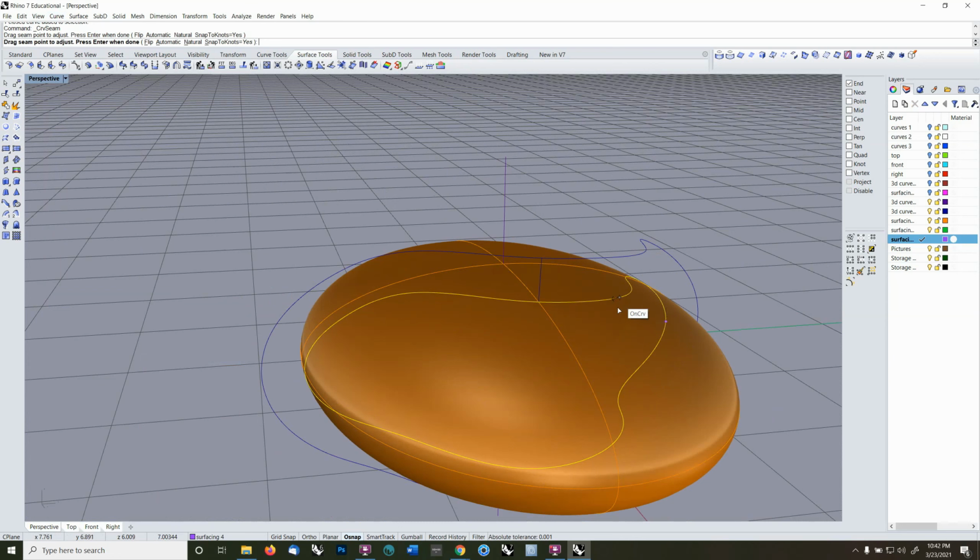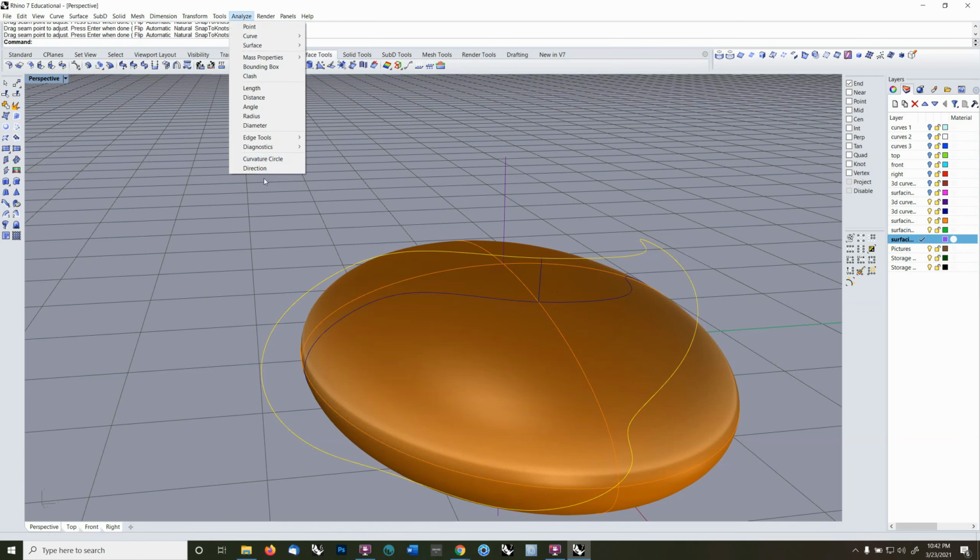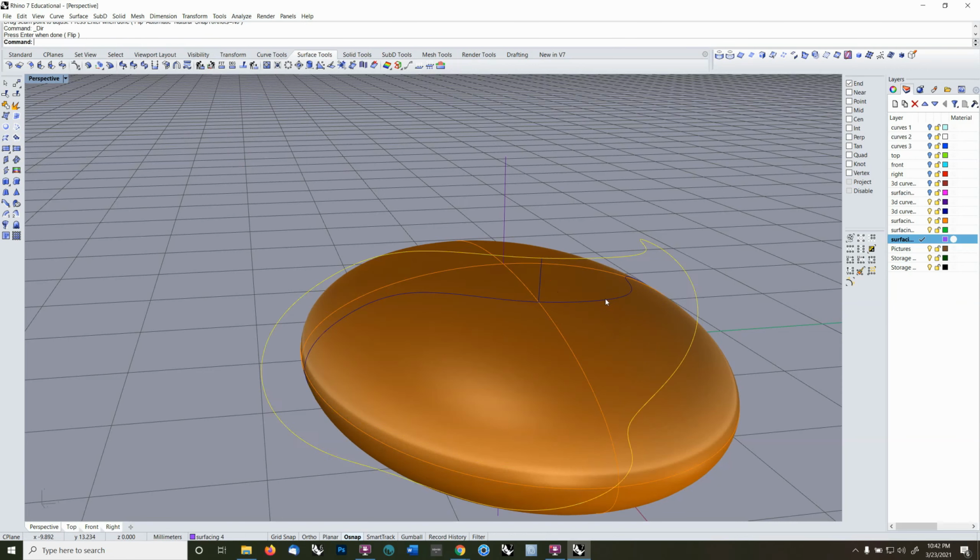It's right here. It's snapping to knots. That's why it won't go. Make sure that's always turned off. Snapping to knots is useless. It's completely useless. You'll notice these surfaces have different directions, these curves. One's going that way, one's going that way. Flip one of them. So they're both going the same way. It'll make your life easier. And now I can do loft.